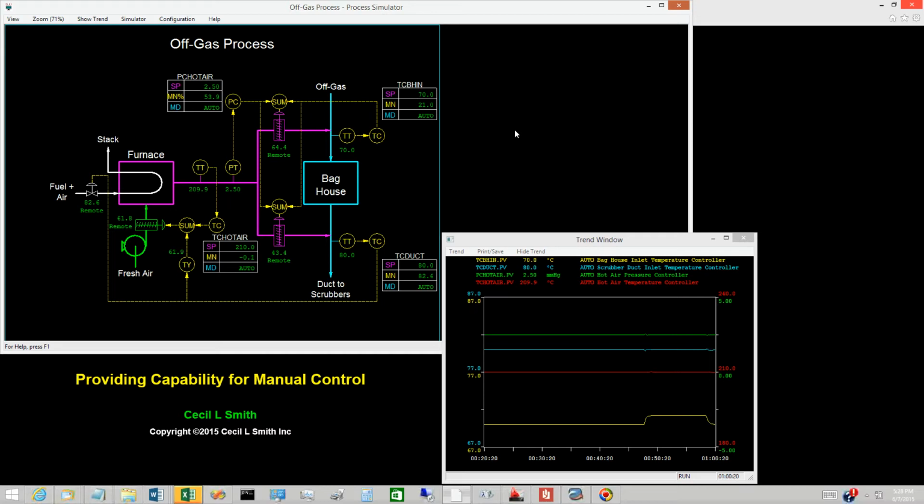Some control systems collect the various functions pertaining to a final control element into what we shall call a valve block. One such function is the fail-open versus fail-closed nature of the final control element. Another function is to permit the operator to assume manual control at the valve block. Such valve blocks have two operational modes.